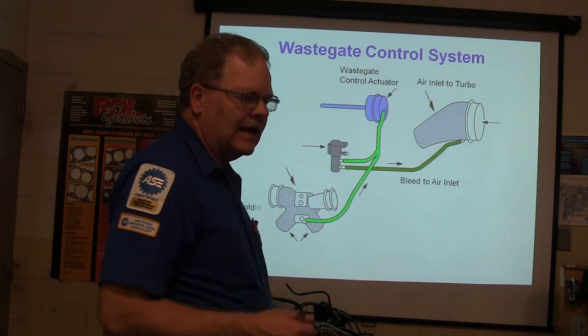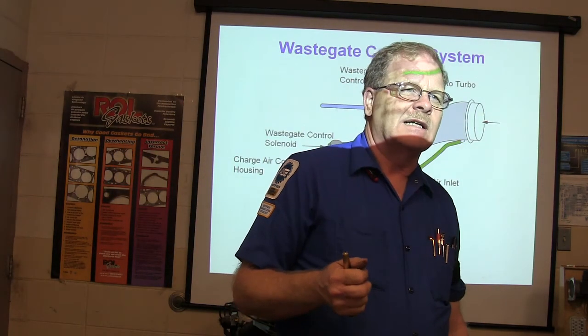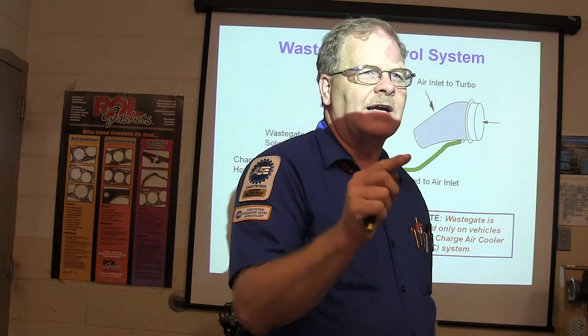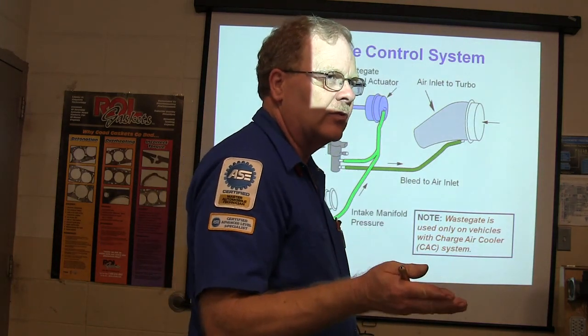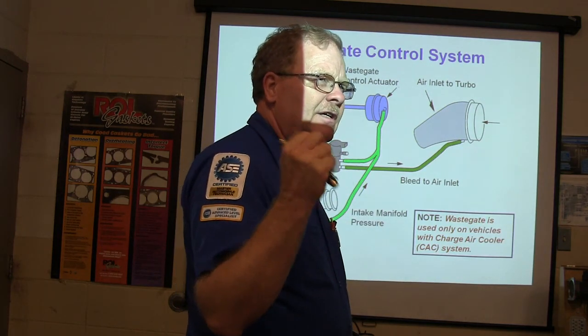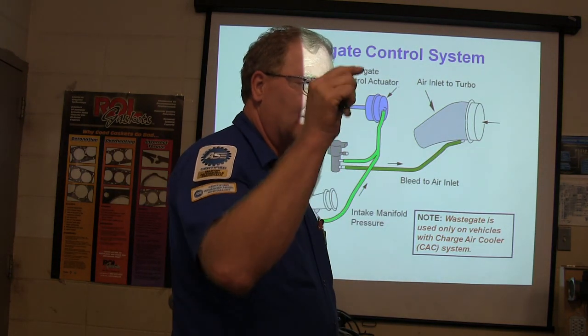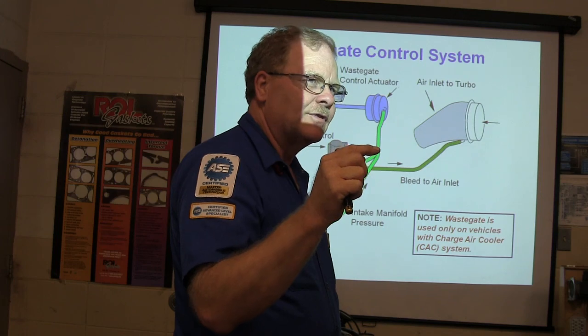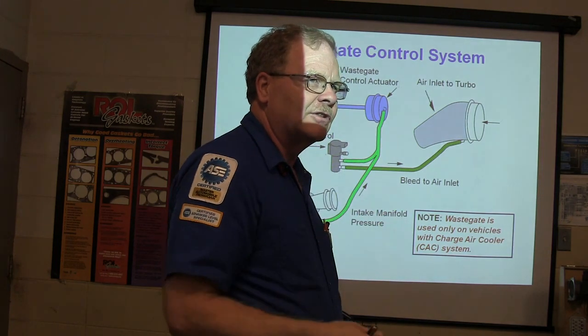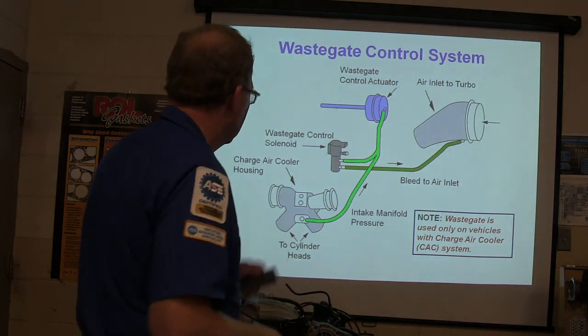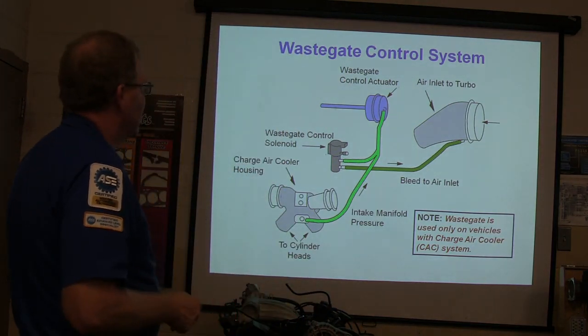Now you remember it's got to have at least 500 PSI showing at the ICP sensor or it won't even operate the injector. It's also got to have more than a certain amount of voltage there, even on these gas burners. You might hear that Ranger spin over if the voltage goes below about 7 volts. When you're spinning it over, it may sound like it's spinning okay, but it won't even operate the injector because the voltage is too low. PCM's watching that voltage.